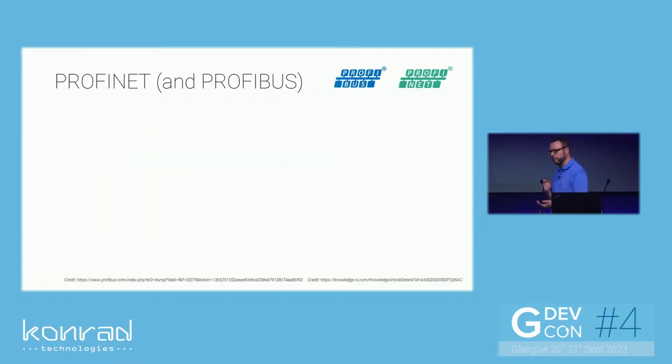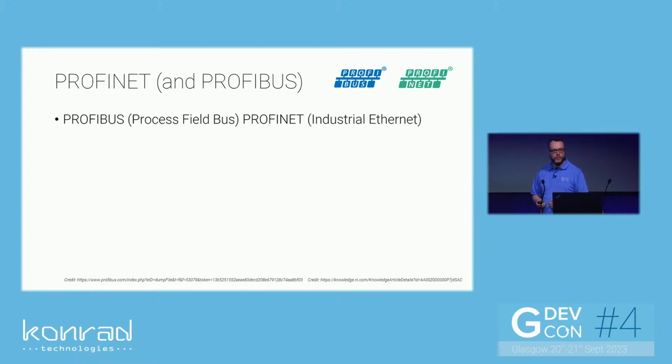So let's start with the first one, Profibus. Now I've got some notes on here because obviously there's some old history and it's quite relevant. So Profibus is the oldest of all of the ones on that list. It's been around since about '89. And it's fieldbus communication for automation technology. Siemens were the early adopters, and they're obviously big players in industrial automation and PLC. There are over 80 million nodes worldwide for Profibus. And it's an openly published standard, so you can go and get that standard and you can integrate to it if you need to do it as a custom.